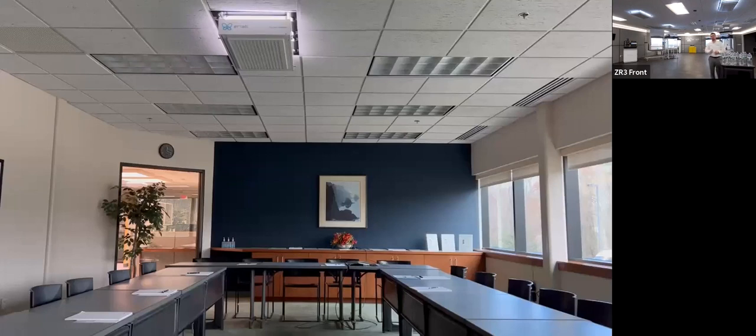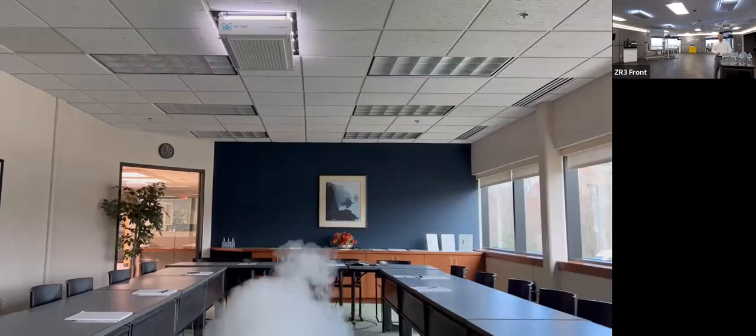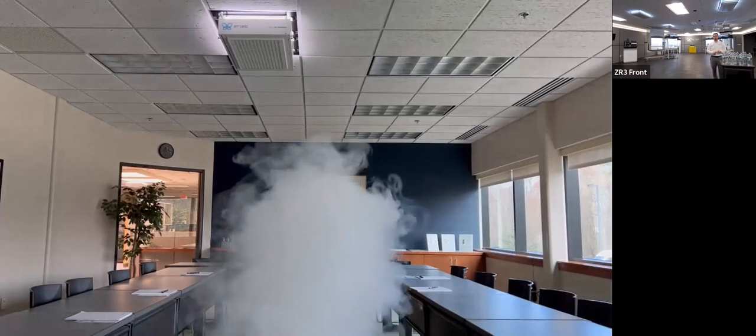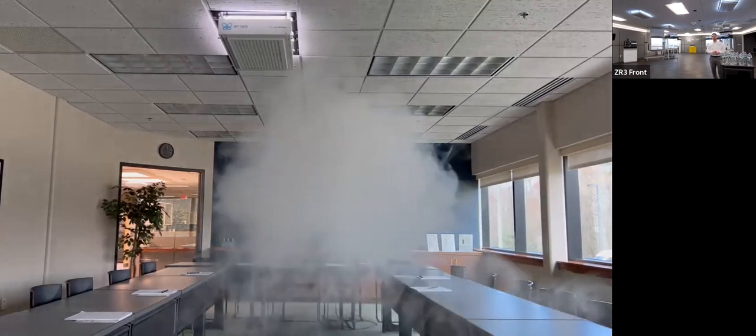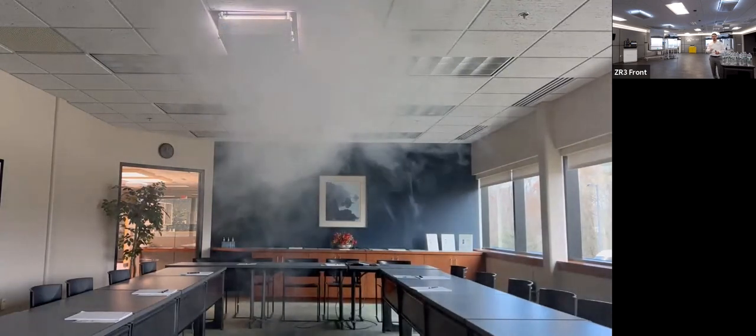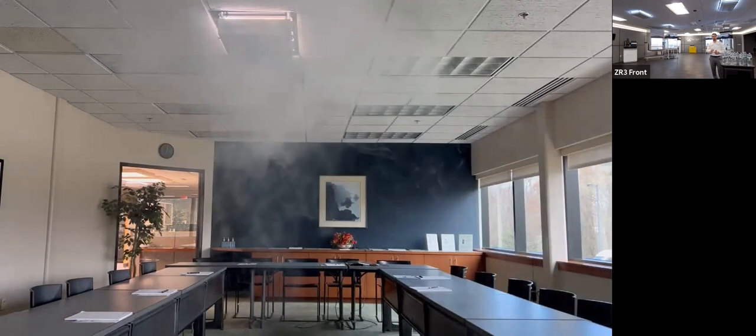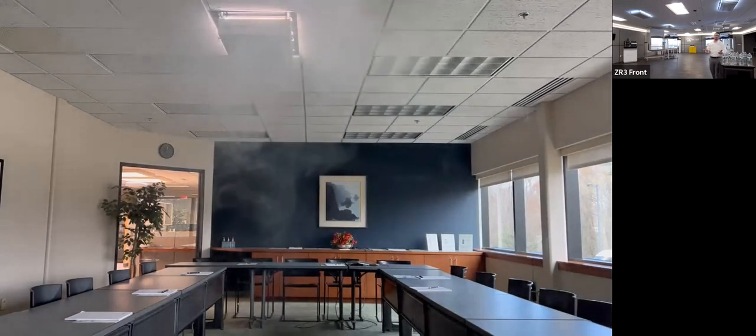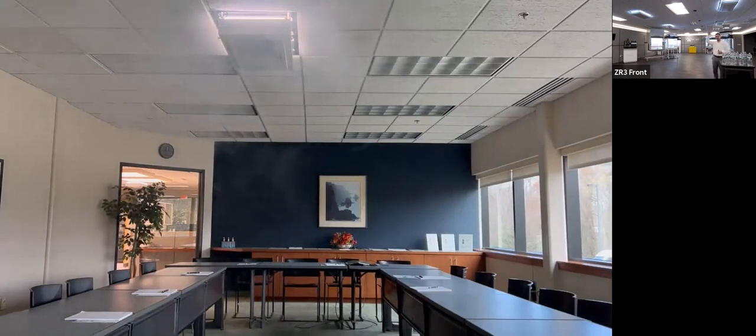The halos, which you saw above me at the beginning of the presentation: if we have the same sneeze or the same infected person breathing and we release these smoke particles, let's watch what happens. Again, we're working with the thermal plume, and it is taking it to the system, eradicating it very quickly, removing it from the breathing zone. This visualization alone shows you the effectiveness of a system that's above the breathing zone that provides proper ventilation effectiveness. Now, again, I mentioned earlier, everything we do and design is based on laboratory standards.